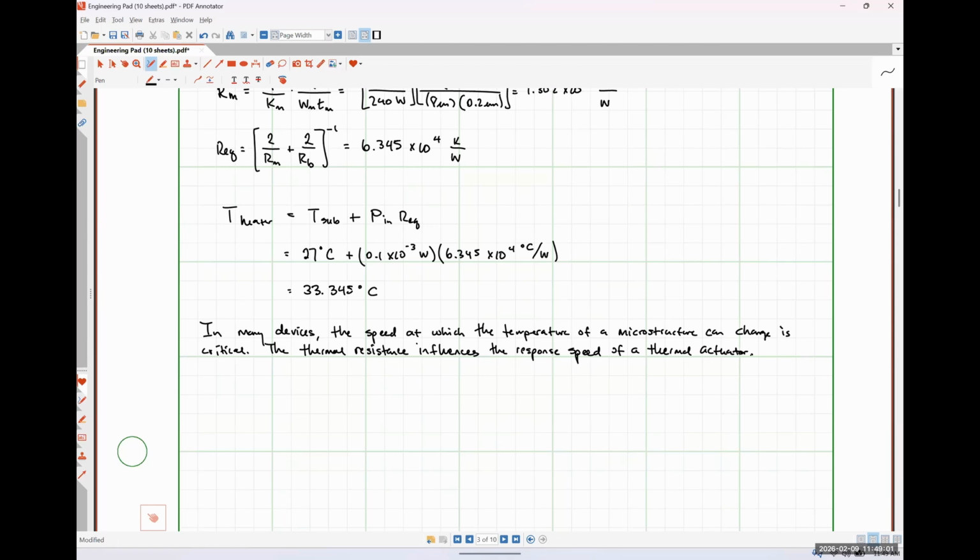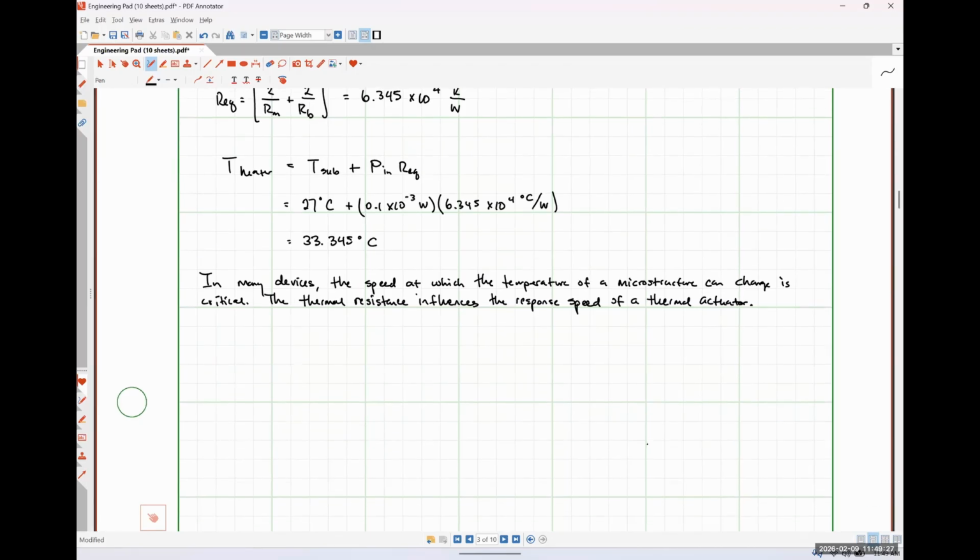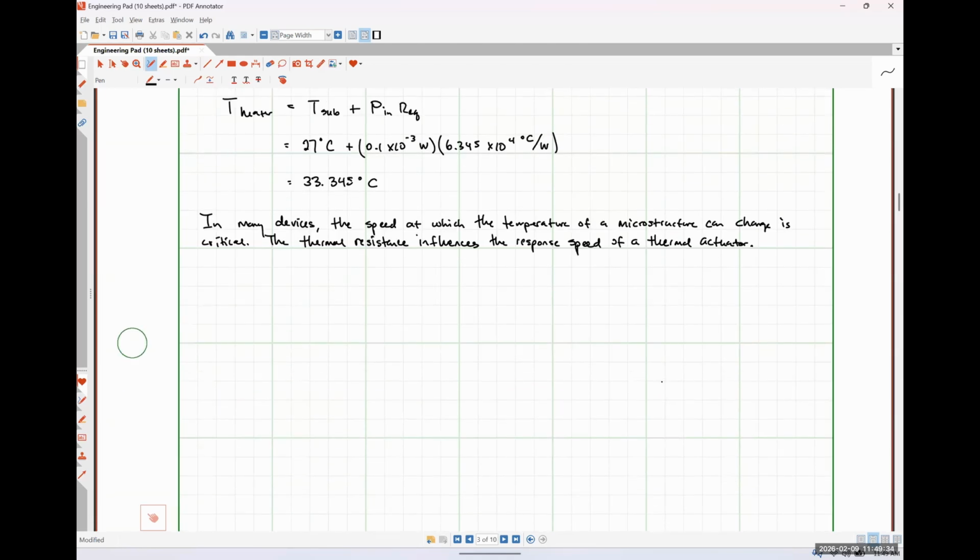So you may recall from our class meeting on, I believe, Friday when we were talking about piezoelectric actuation, I mentioned that it happens instantaneously. Well, this is a case where it very much does not, right? It takes time for heat to be transferred. And so it's going to take time for our actuator to respond to that change in temperature. Okay. So the mathematical relationship that relates our stored thermal energy and the temperature change is as follows.